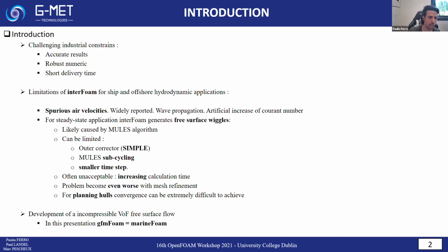This is likely caused by MULES algorithm for wave capture. Interface wiggles can be limited by increasing outer correctors, MULES subcycling, or using a smaller time step. But this is often unacceptable because it leads to a large increase of the calculation time. And the problem becomes even worse with mesh refinement. For example, for planing hulls, convergence can be extremely difficult to achieve. So in this context, we decided to develop an incompressible free surface flow solver, which I will call GFM foam or marineFoam in this presentation.